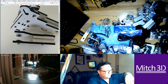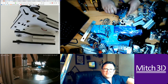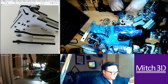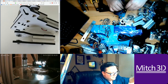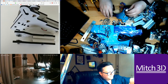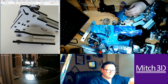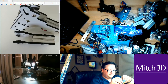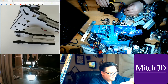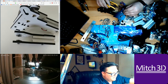Okay, so let's do another motor pulley. So these are actually loose. The motors are loose so that I can tension the belts. But I'm going to do another motor pulley with the flat here. Push this down, make sure it's flush. Take my 2mm hex.